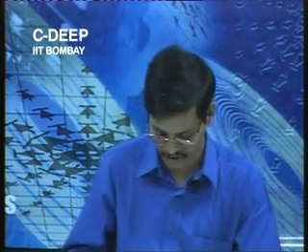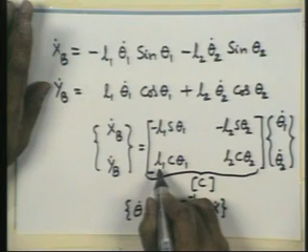where I am saying x dot to indicate the x and y components of the velocity of the end effector tip, and theta dot to indicate all the joint space velocities theta 1 dot, theta 2 dot and so on and so forth. Now, this matrix C is typically of this shape.